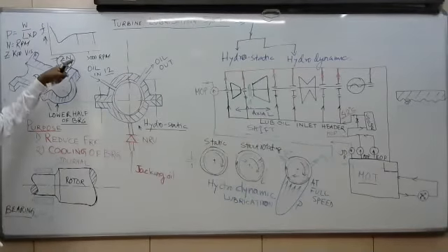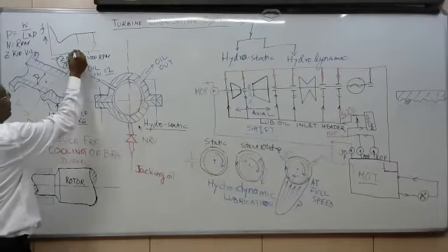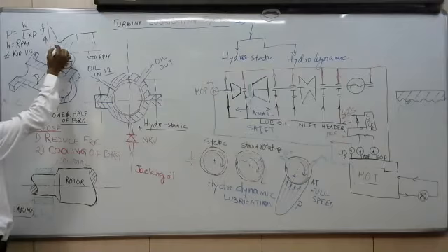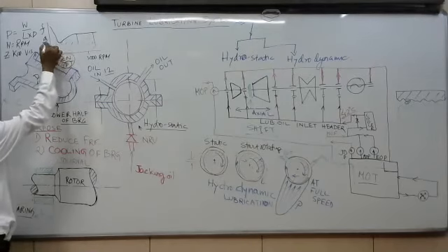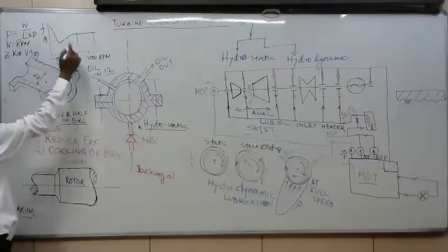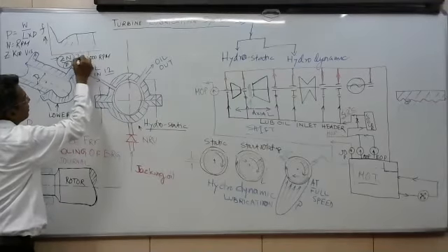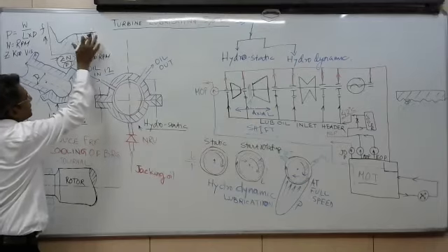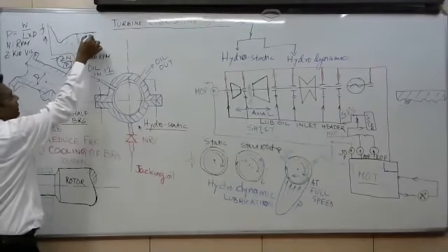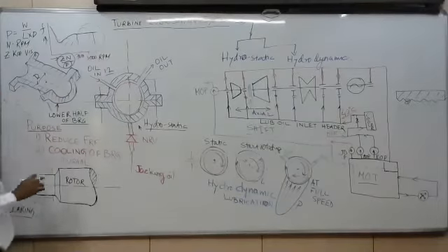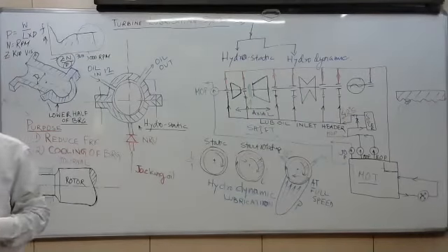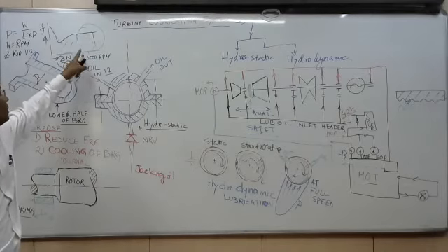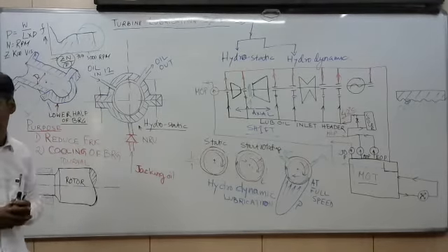So by this we are plotting. This is the lower range of RPM where hydrodynamic lubrication doesn't take place. The friction is lower, but it is hunting. It is not a stable area. After a certain RPM, suppose 700 RPM, we are achieving this much friction at stable condition. So that is the hydrodynamic lubrication zone we have achieved. By this curve we are actually designing the hydrodynamic lubrication bearing, and at 3000 RPM, what is the friction zone over here?